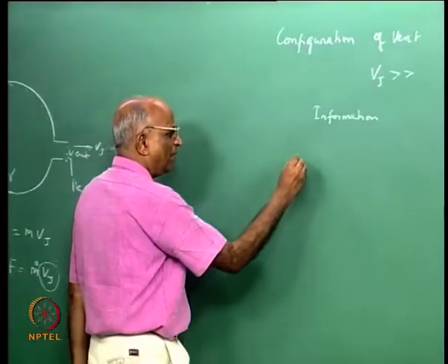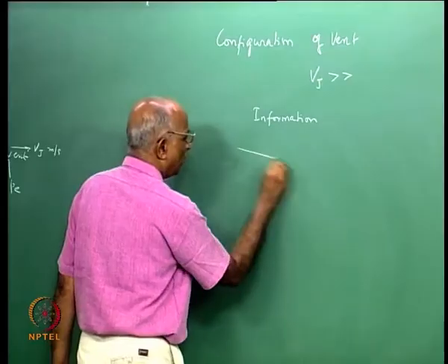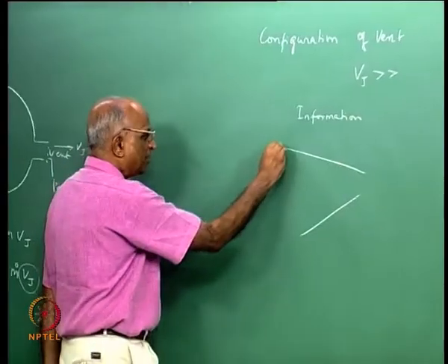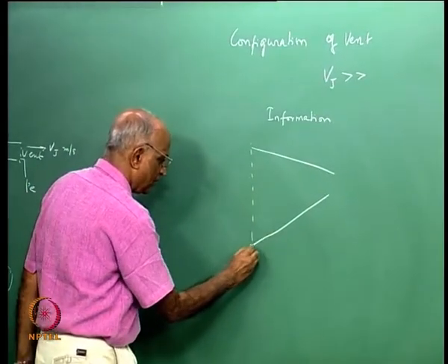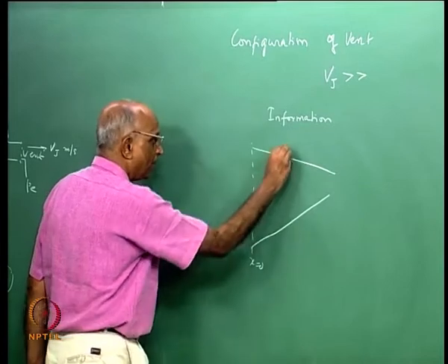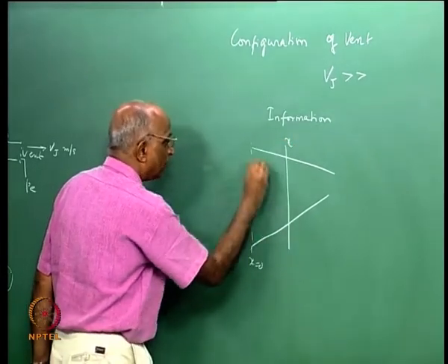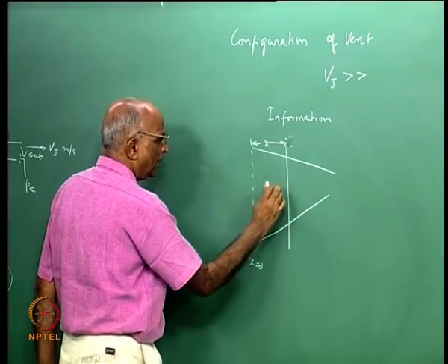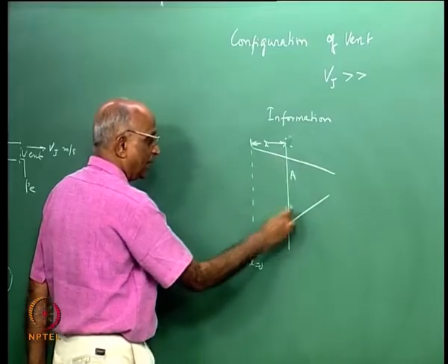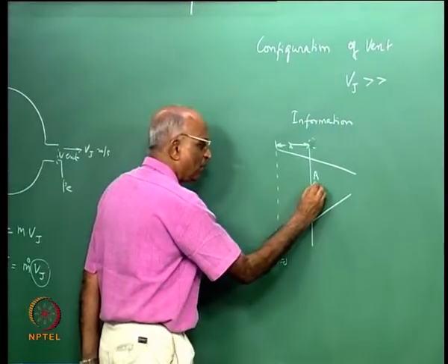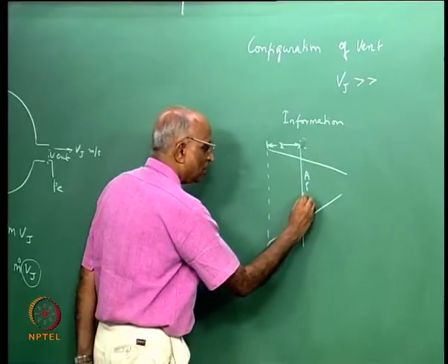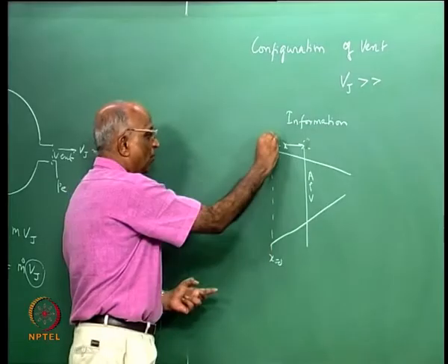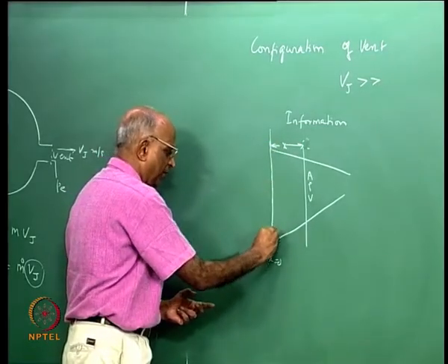Let us first say, well, I have a nozzle, and in this nozzle I am interested in the shape, therefore I say, well, let me have a shape like this. The shape is such that, let us say this is x equal to 0, at a distance x from the initial origin, the area of the vent is A, let the density of flow through this be rho, let the velocity of flow be v at this particular section.